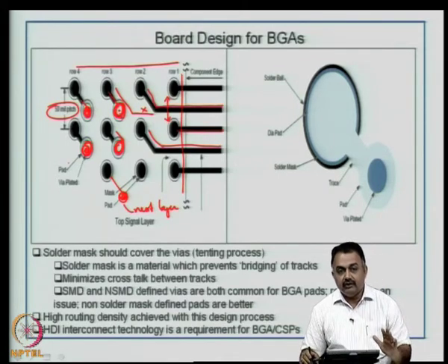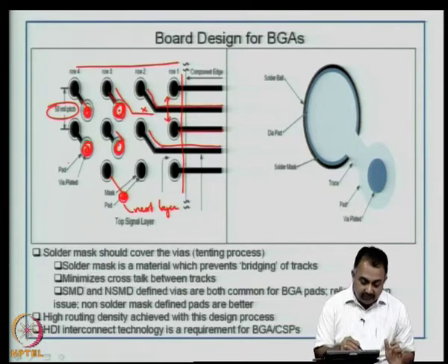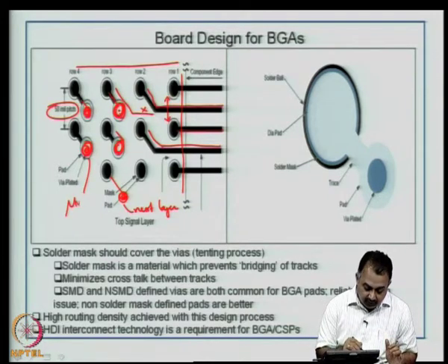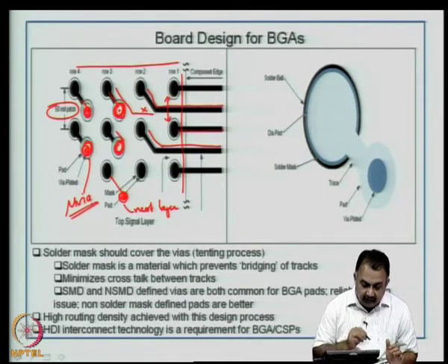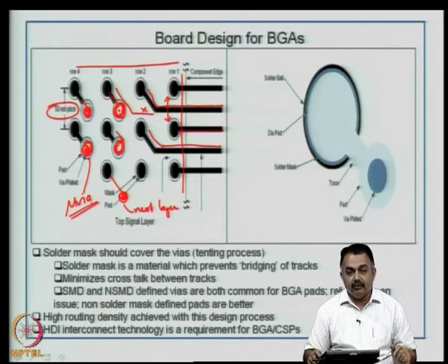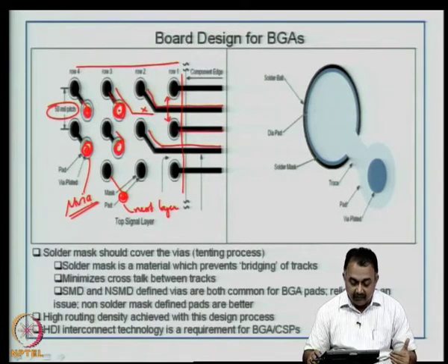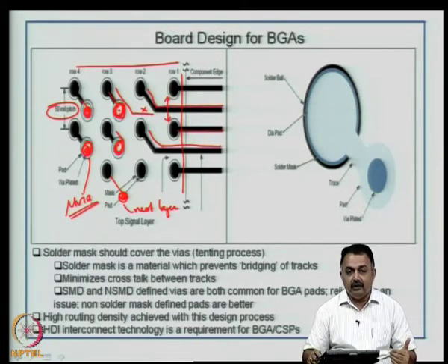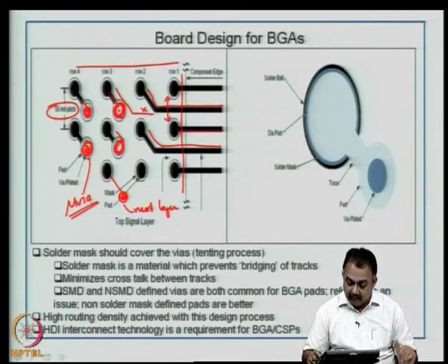So, you need to know about creating this. This is typically a micro via that you can do. You need a small via, you can't use a very large via structure here. And typically for improving the reliability of this design, you want to use a micro via using a SBU technique, which I will explain when we come to manufacturing, and typically you do not want a through hole structure.